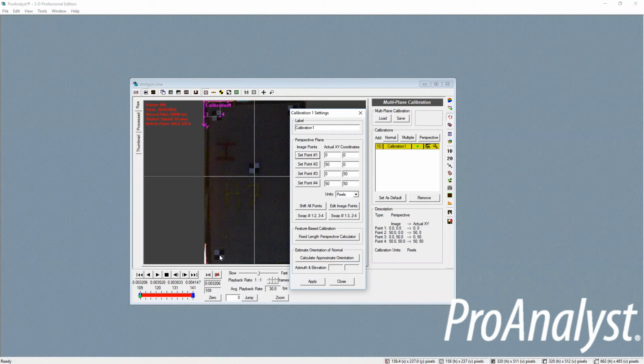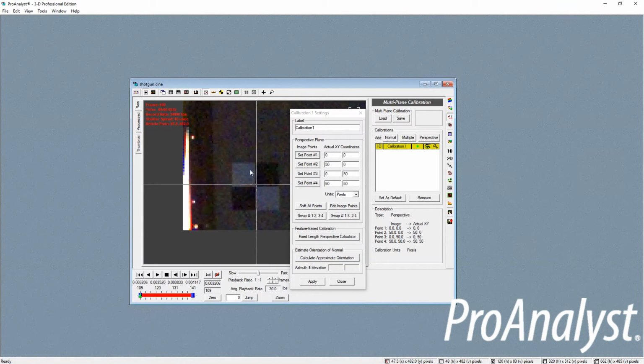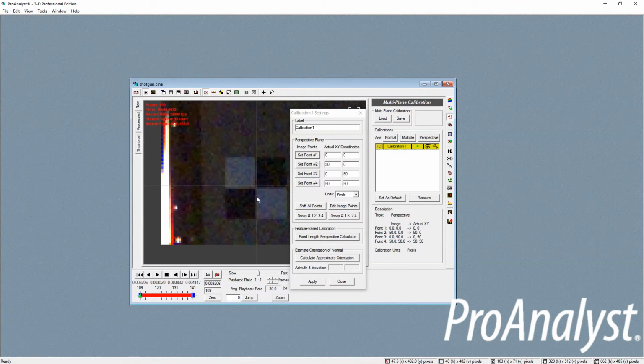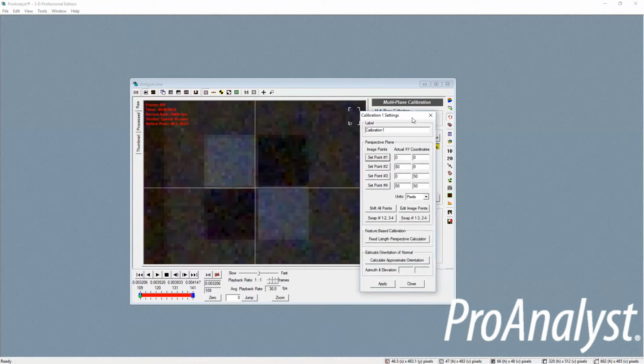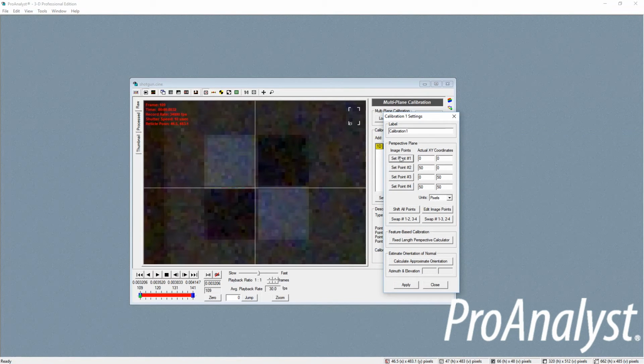To do this, center the reticle over the point of interest and click. You can now zoom in using the scroll wheel of your mouse to further refine the selection. Once you're satisfied with it, click on Set Point. This point is at -15 and -36.